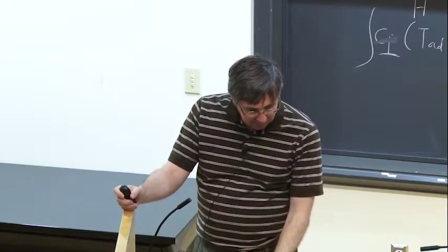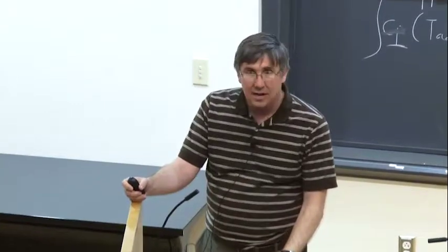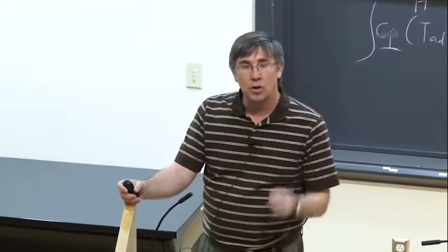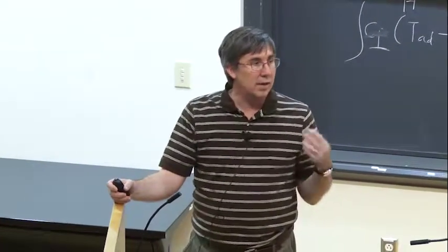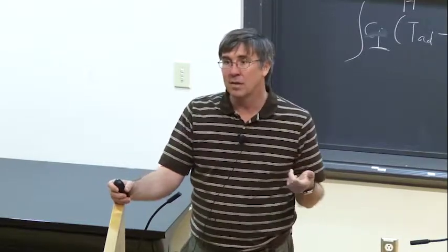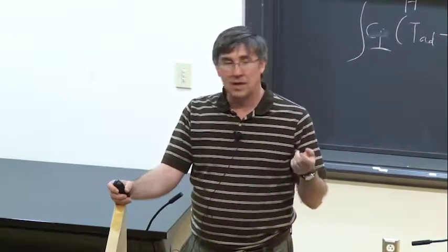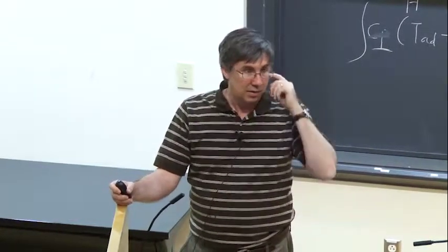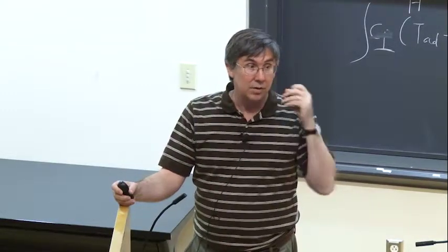So a key thing is you have to get the oxygen there while you still have ethylene and propylene. If you wait until you make all propargyl and acetylene, you're going to be too late, because then you're going to react and make soot. And then you're going to have a lot of trouble, because you're going to make particulates.